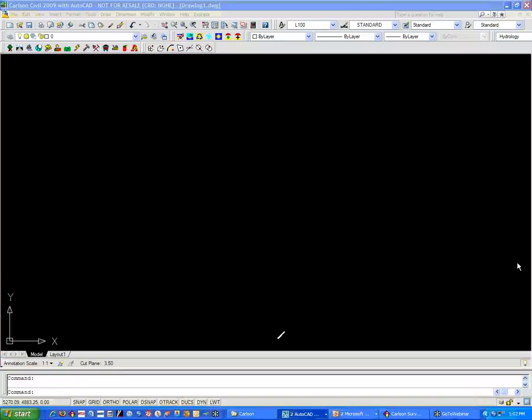So if you try 100 scale and it doesn't work, you may need to bump it up to a 200 scale. And so that would be your viewport scale. So you're kind of scaling that viewport window instead of scaling the title block up around it. The benefit to doing that is that, again, using the example I did a minute ago, you may have an overall site plan that's a 1:100 scale, and various and sundry plan and profile sheets are at 50.